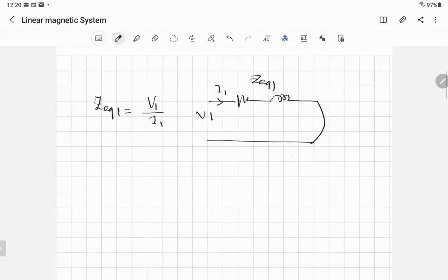But just to make sure, because the first group, when they exceeded the current, I think it exceeded the rating value of the transformer, not the other components. So try to make sure the short circuit current does not exceed 0.3 amp. Okay, that's the first thing.